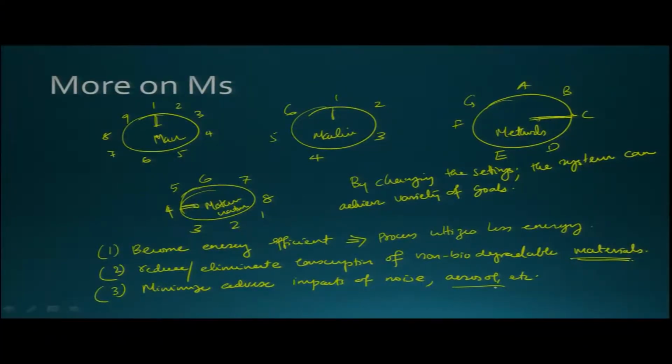An aerosol is where the spray or, let us say, for example, your process has a very high speed cutting drill or a drill bit which is running at a high speed, and the coolant, when it comes in contact with that, will actually become very fine particles or a fine spray which becomes an aerosol. Most of these cutting fluids are chloride or sulfide based mineral oils, which can actually create a much dangerous health hazard to the worker. So, here you are thinking about the man aspect, the human aspect, the better work environment, those kinds of stuff.